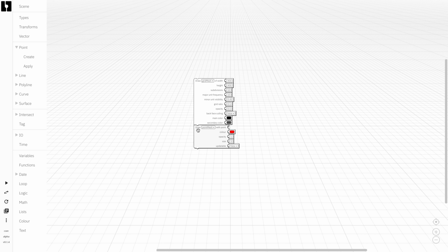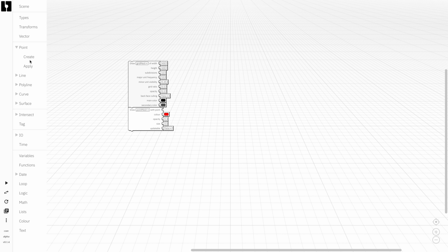And so this point drawing component asks you to create the point itself. How BitByBit handles the drawing is that it also assigns the point that is visualized into this point mesh component, so you could keep track of it and update if needed. That's a bit more complicated concept, I guess. I will have to explain that in more detail later on, especially when we will be dealing with rendering loops.